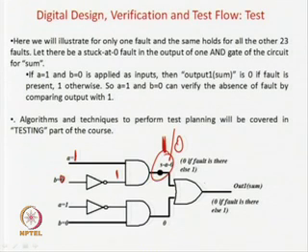Similarly, it is an OR gate, so you can put A equal to 1, and the other input 0, so the answer is a 0 over here. So this is the sum. In structural testing, you do not think about the functionality. If the fault is not there, what will happen? 1 or 0, the answer will be 1.